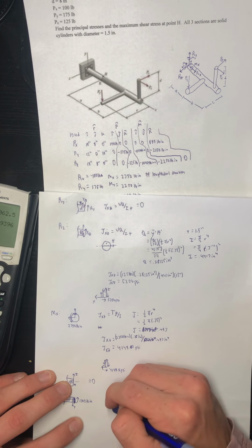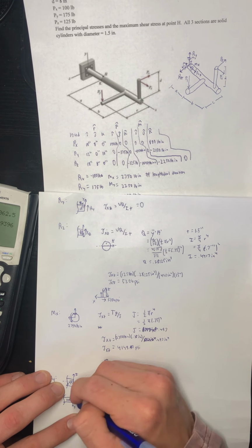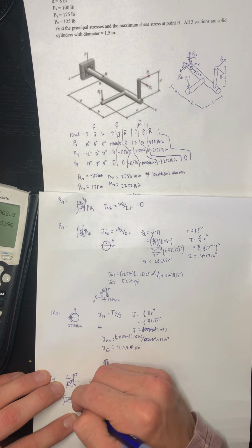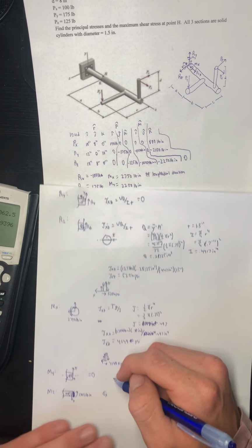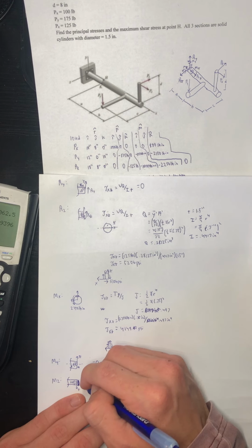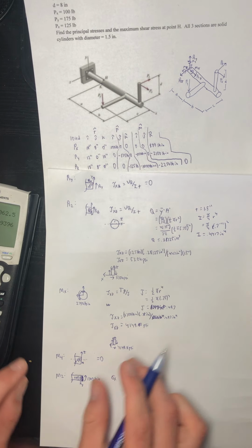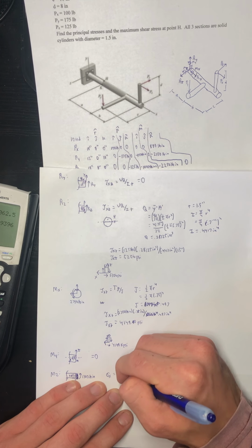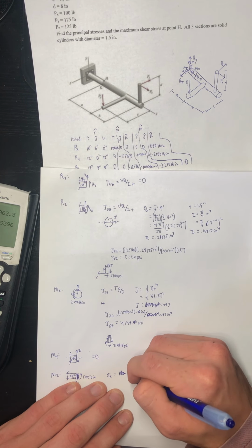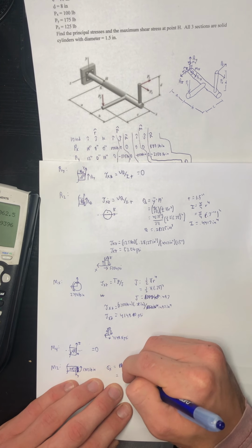All right. So, let me see here. Our stress that results from this, our differential is then going to be on the bottom because it's perpendicular to that y-axis. So our stress is going to be in tension because the bending is pulling on this side outwards, and it's compressing on this opposite side. So we have our stress in the X is going to be equal to My over I, which is equal to